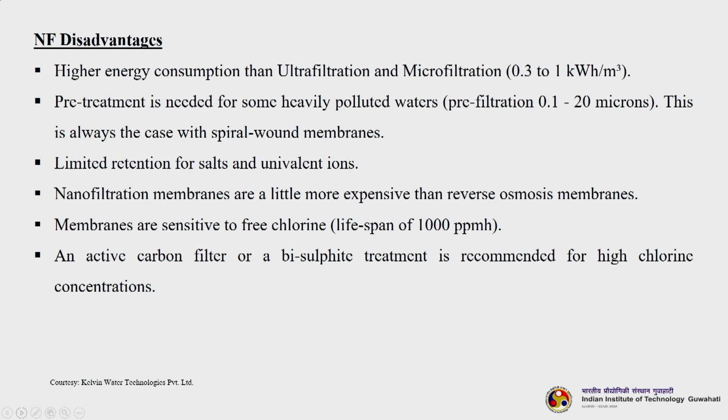So, it has certain disadvantages also. Higher energy consumption than ultrafiltration and microfiltration, almost 0.3 to 1 kilowatt hour per meter cube. Another important thing is that pretreatment is required for some heavily polluted water. So, prefiltration 0.1 to 2 microns, all these things need to be removed, otherwise your membrane will be clogged and it will not give the targeted performance.